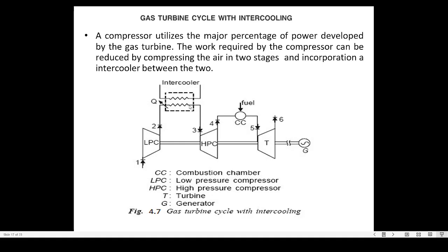So here we normally have a counterflow arrangement, and most commonly water is used as the coolant. The heat exchange takes place between the high temperature air and the cold water, which is circulated through the two different channels of the intercooler. So this is a counterflow arrangement, right? The air flows, let us say, through this lower channel from left to right, whereas the water may enter the channel on the upper side from the right and leave at the left end of this arrangement.